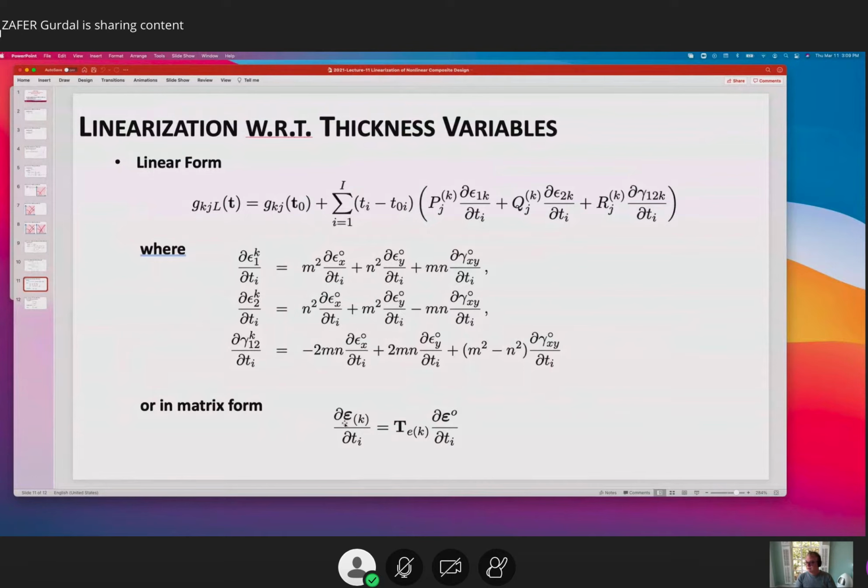And what you use in there will typically be the same. So if I want the stresses along the XY directions in an individual ply, I can directly go to my laminate expression or layer expression and put the strains in there and compute.